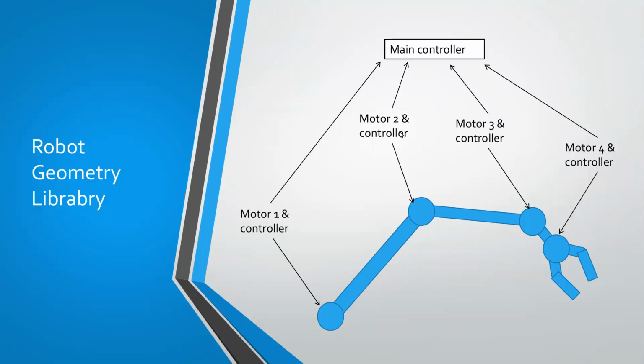If you use an STM32 or an Arduino for this controller, you need a separate motor controller for the motor. But if you use a specifically designed control board, it will have the voltage and current control capabilities as well as the communication and calculation capabilities built in. If you search on the internet, there are some boards like that.